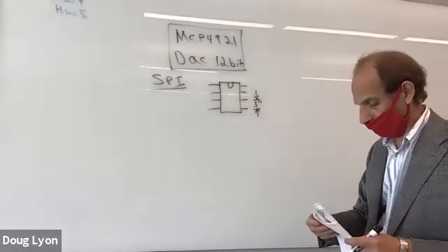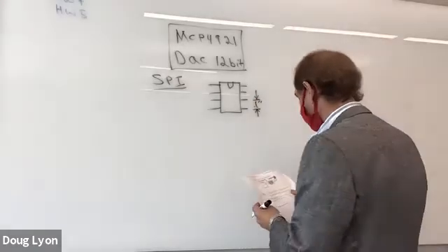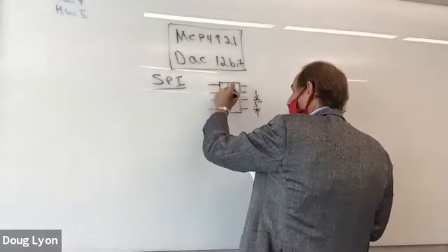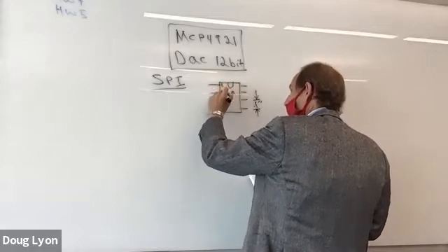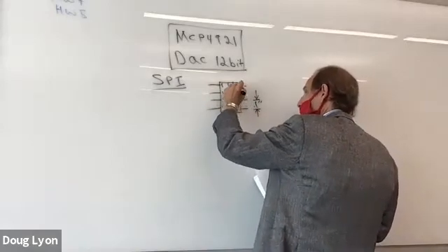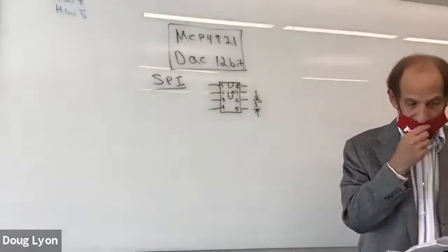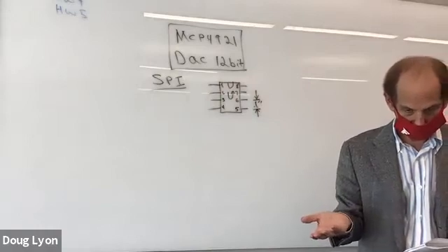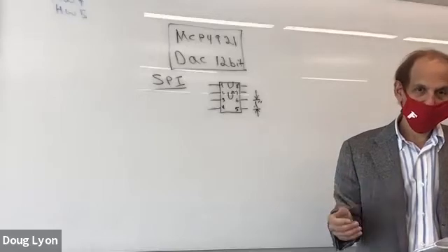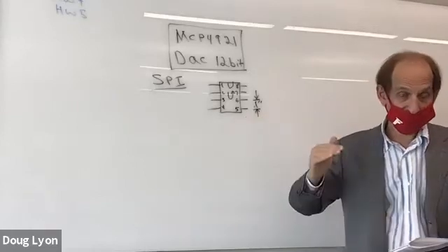So what you're looking to do for your basic DAC application is you're looking to get the pins. The pin numbering starts at the left and works its way like a U. 1, 2, 3, 4, then across 5, 6, 7, 8. The pins for a DIP are very convenient for your breadboard, but are kind of inconvenient for manufacturing, because when you are making a printed circuit board with the so-called through-hole pins, you have to drill a hole for each pin.